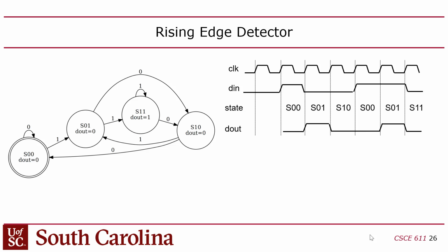So the way I did it was I created one state to represent the last 2 input values. So I have a state 0, 0, which meant the last 2 inputs are 0, 0, right? Now, this is where that delay comes into play, though, because if I'm in state 0, 0, that's also the reset state, too. That's why I used a double circle there to indicate that.